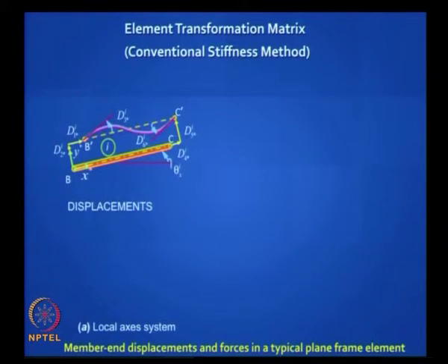Let me explain once more, and please listen carefully, pay attention. This is what we did in the last class, right? Here you have 1 star, 2 star, 3 star and so on. If this joint has moved here, the displacement along the local x axis is d1 star, with the i standing for the ith element, and this movement normal to it is d2 star. Is it clear?